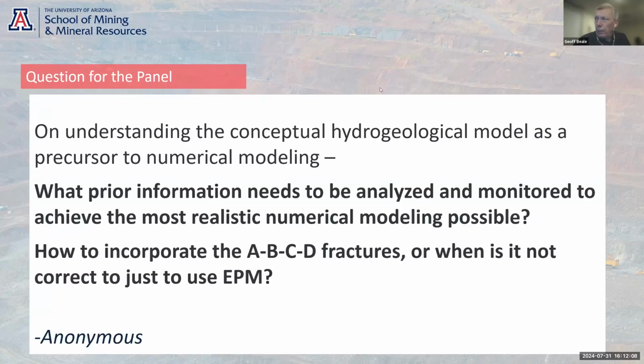But that's a special case, and what we're going to do with that is actually just take a fracture flow model and look, not at a wider scale model, but at some specific simple 2D situations, to try and understand the difference in cooling or thermal transport. We'll set up a 2D model with an EPCM, and we'll probably set up a 2D fracture flow model, not to look at absolute results, but to look at the difference in cooling between the two models. So that's one very rare example where you might need to look at a fracture flow model.